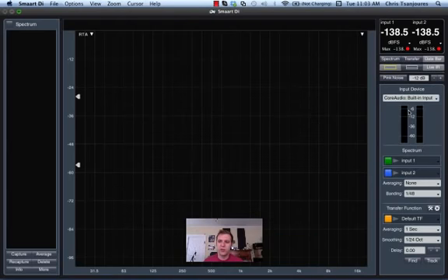Okay, so the way that we are getting measurements in DI is basically there's two spectrum engines which are paired to one transfer function engine. So when you launch, the default configuration is input 1 and 2 on the spectrum, which are tied to measurement and reference of the transfer function. So input 1 is a measurement and input 2 is a reference signal.